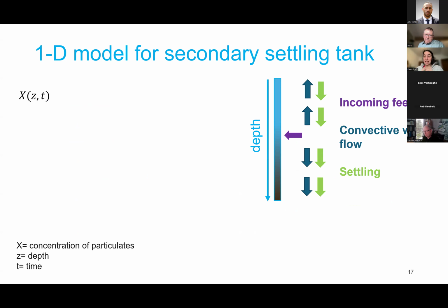You see that we actually only consider a single variable, which is solids, TSS, particulate material. So if you couple this to a biokinetic model, what you do at the start of your model, at the interface, is lump all particles or all particulate fractions into this one solid fraction. And the soluble components will just flow with the water. So they will not settle. So that's a little bit how the interface would work with the biokinetic model. Within the settler model, we consider only one variable, which is the solid concentration, which varies over time and over depth of the column. Since it varies over both time and depth, we describe this with a partial differential equation.